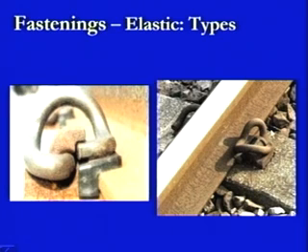Here you can see another photograph where the rail section is clearly shown. Here there is a sleeper, and through this sleeper we have used this clip. So, this is the location at which it is putting the pressure, and the pressure is so heavy that the rail section cannot move from its location.